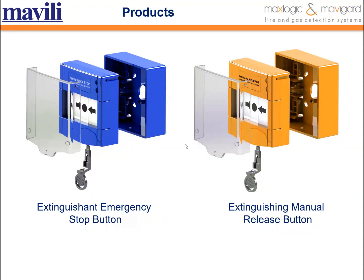Here are the two products that are necessary for the extinguishing: emergency stop and extinguishing manual release button. If necessary, extinguishing release is initiated by the user, and the emergency stop button is designed to hold the extinguishing. If there are people working continuously in the location, these call points should be designed both inside and outside the location. Otherwise, it will be sufficient for the set buttons to be at the entrance of the location.